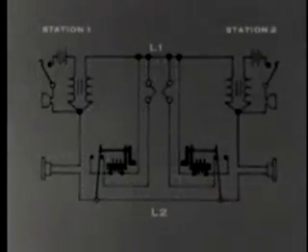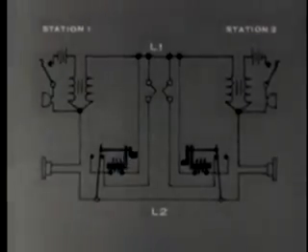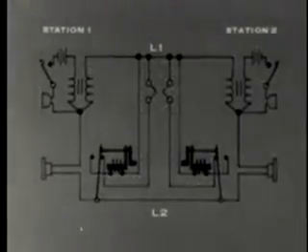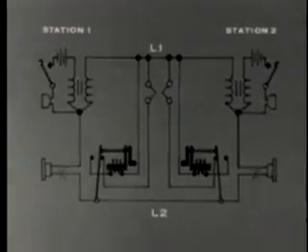But there is something missing in this circuit, because when station 2 rings station 1, the current in our receiver circuit overloads the receiver. The same thing occurs when station 1 signals station 2. To correct this, we must make use of our sixth basic component, a capacitor.